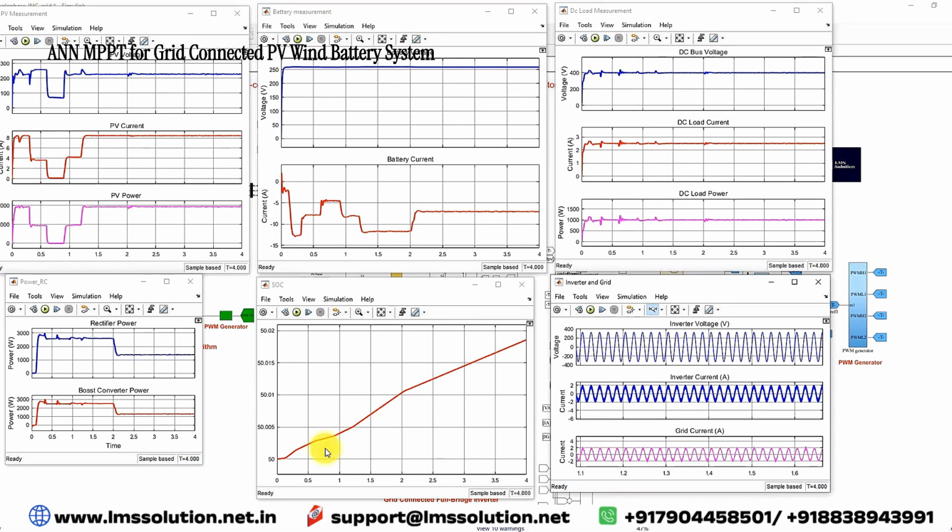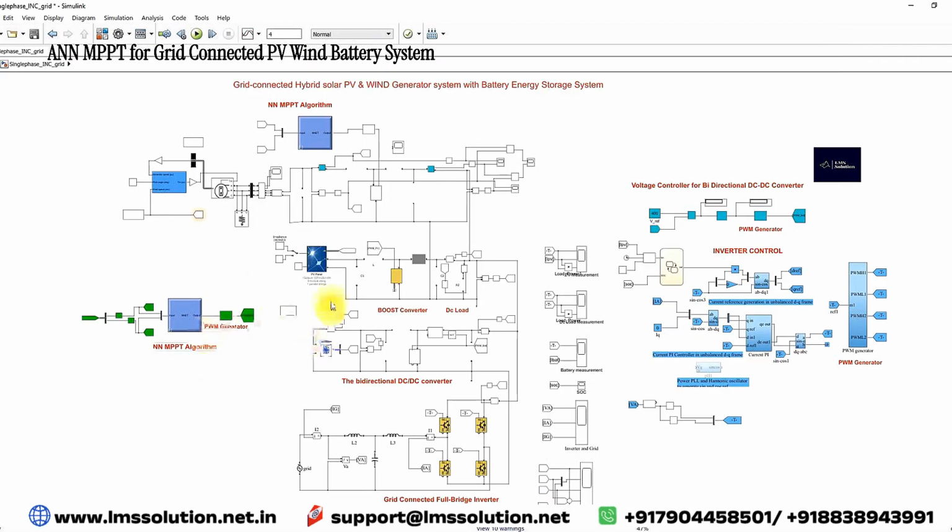That's why, in that condition, we are not yet taking any current from the grid. So we are sending current to the grid only. That's why the inverter current will be maintained at 2 amps peak. And you can check the phase angle, right? Both are in phase. In phase means the DC microgrid is sending power to the AC grid. It's a concept.